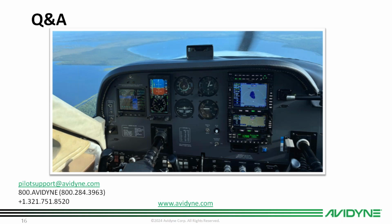One of the other questions I get, it's not on here, but we get a lot, is can I use the IFD 550 as a legal standby? And I want to emphasize that the attitude reference sensor and the attitude display in the 550 is TSO'd. In other words, it meets all the TSO compliance. We can't take credit for it as a legal standby, meaning you can't get rid of your other standby gauge, because we can take the attitude display down on the IFD 550. You know, you can switch to a map or some other screen.